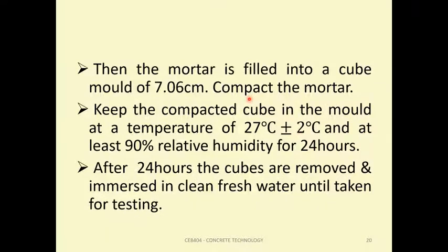The mortar is filled in a cube mold of 7.06 centimeter and compacted. This compacted cube is molded at a temperature of 27 degrees Celsius and a humidity condition of 90%. After 24 hours, the cube is removed and immersed in clean water until it is taken for testing.